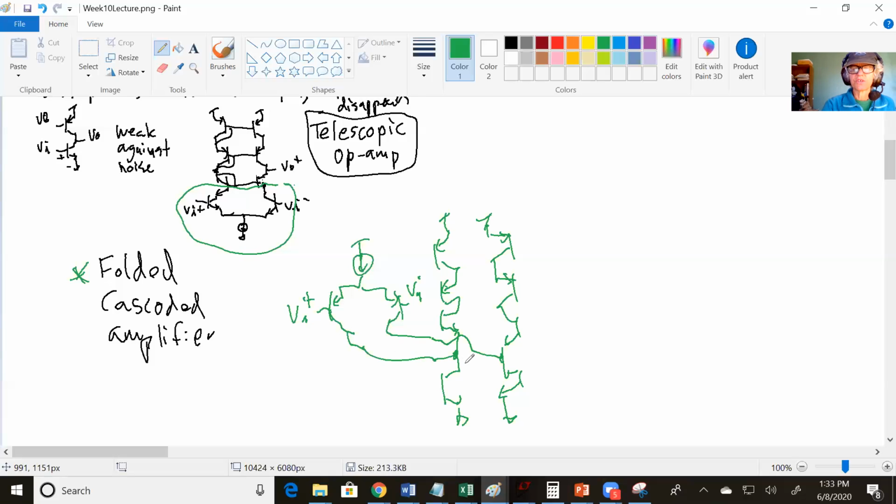And these currents change the current through these bottom transistors, and therefore the current through the top. So instead of having the transistor that changes the current in series with all the other transistors, it's over here just either injecting current into a side or not.